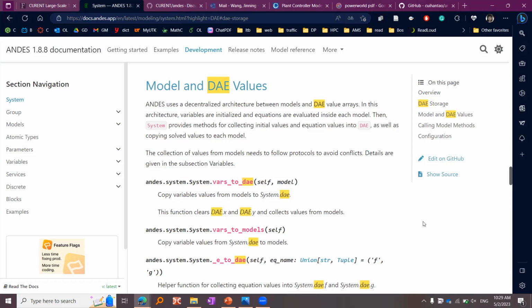So what he's talking about is what we did in class, right? What I described is what is done in PSSE and PSLF, where you're going back and forth between the dynamic equations and the algebraic equations, right? So that's more limited. By solving them together, you can be faster. But anyway, what I described in class is what, as far as I know, all commercial software does.